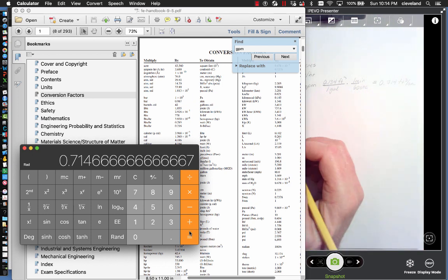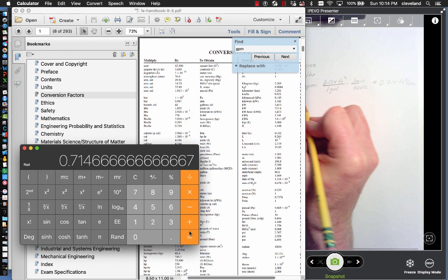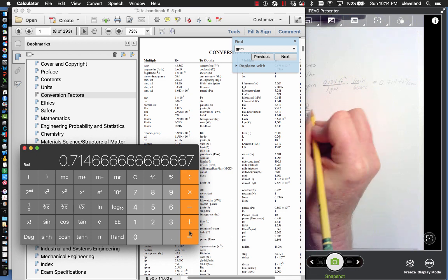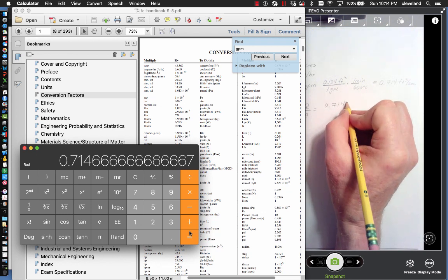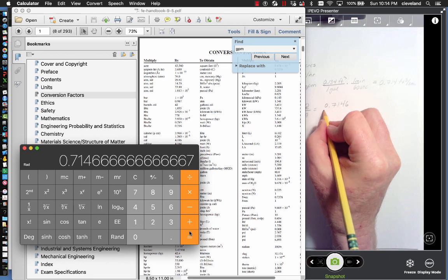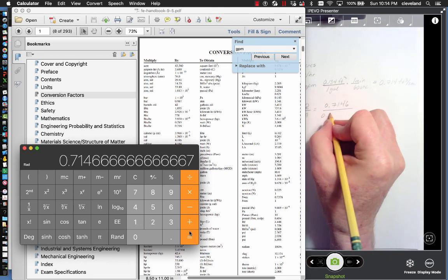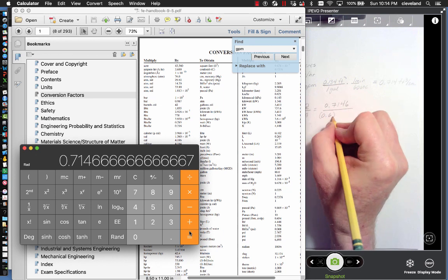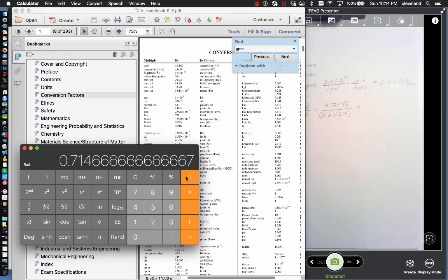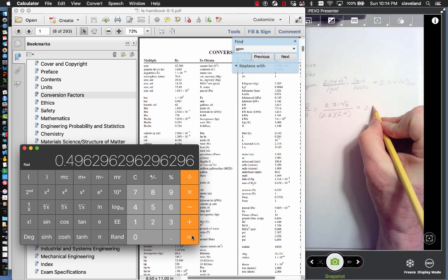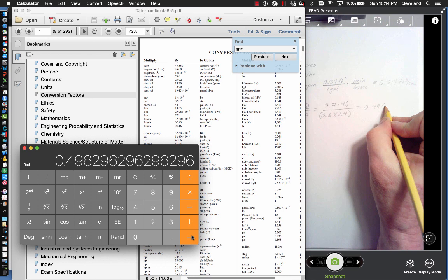And now we'll rearrange the equation and solve for C. C is equal to Q over I times A, which equals 0.714, divided by 0.6 inches per hour and 2.4 acres. Divide by 0.6. Divide by 2.4. And it says that we have a runoff coefficient of 0.496.